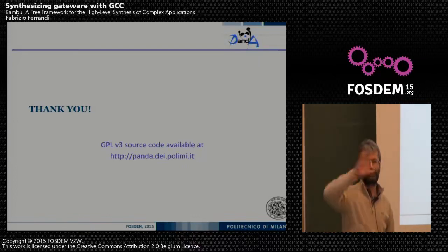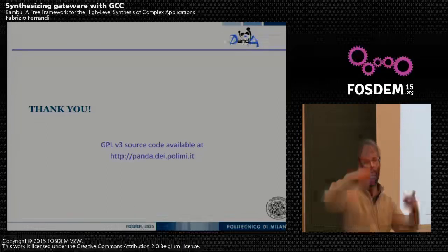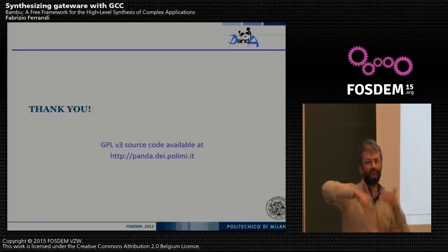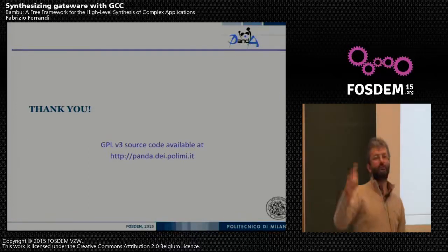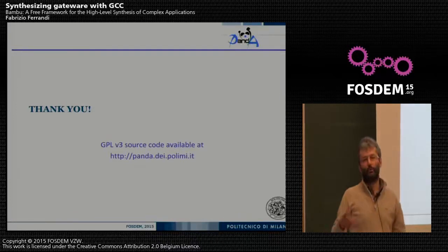Since we have a modular allocation, we use what GCC does to figure out the size of the element and so on. We have developed some units that are able to support aligned and non-aligned access to the memory, more or less as a processor does. So there is a bus where we put the address, the memory returns the data, and so on and so forth. That works, and works pretty efficiently.